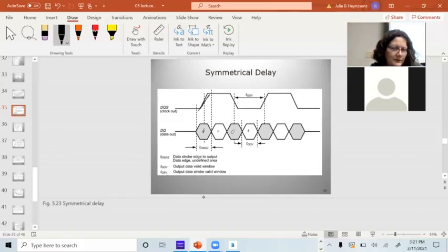Yes. Is there an advantage to having skew on it, or would it be better if it was a perfect square wave? If it's a perfect square wave, it's going to have more high frequency components. If you slow it down, you get rid of some of the higher frequency components. The other problem with perfect square waves is, think L di/dt. If you're switching the voltage, you're switching the current going through that line really fast, you're going to cause larger voltage spikes. So skewing it a little bit gives you smaller spikes on your lines. It helps clean it up.